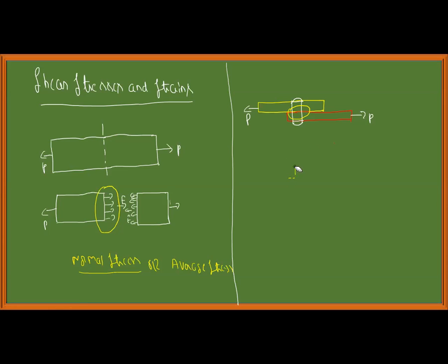If I take the upper part of the rivet, there are shear stresses built parallel to the surface, and if I take the resultant of this as Ft, the shear stress is given by the resultant force Ft divided by the unit area of cross section, or generally force per unit area.